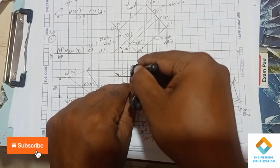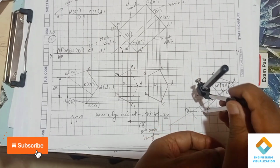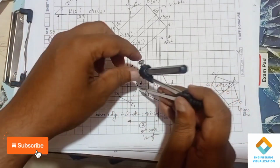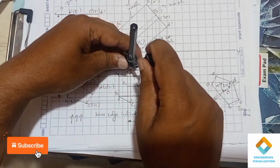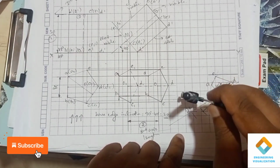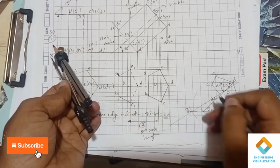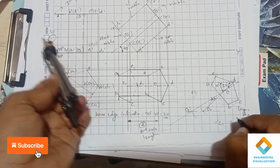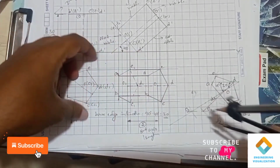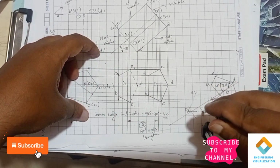So measure from O1 to E1 and O1 to C1, and cut it here and here. Now from D1 to E1 and D1 to C1, cut here and here, and mention these two points as E1 and C1. Now again from O1 to A and O to B, these two lengths will be the same. Cut the arcs here and here.